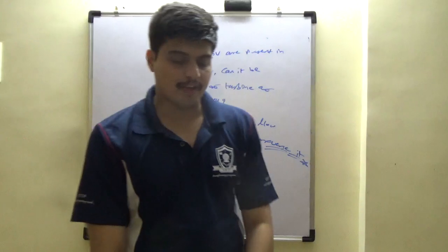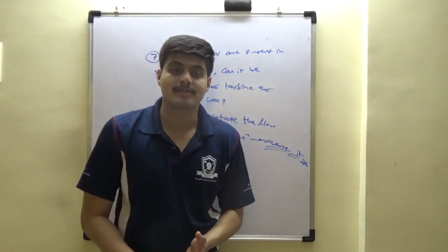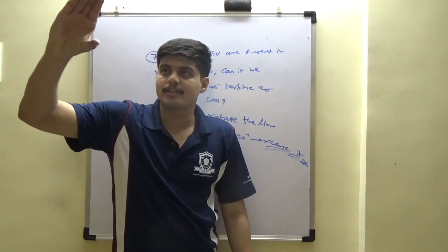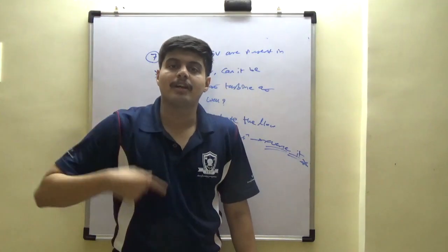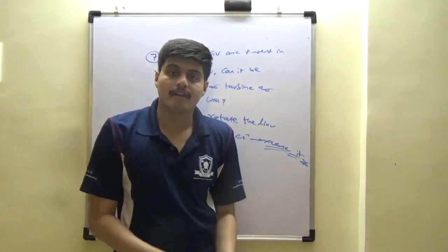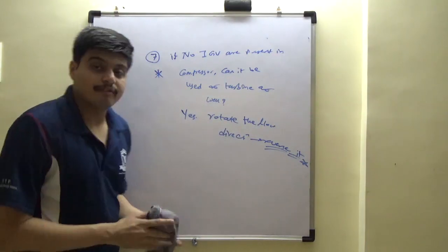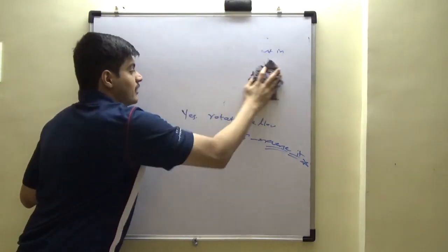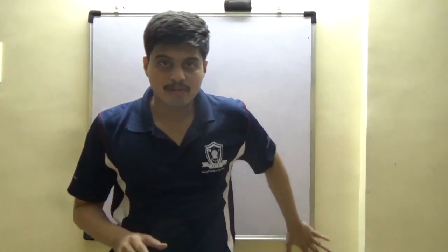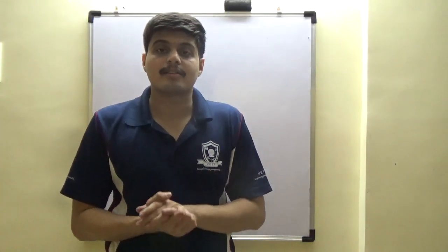Mechanically, there are of course a set of challenges. Something called turbine compressor matching through spools. The hub radius which increases here would not allow your turbines in a small concentrated zone to operate with such a high temperature. So the material science guy there and the mechanical engineer guy there will not let you do it, but propulsion engineering can let you do it. So this is a very good question to understand the nitty-gritties of axial compressor. This closes our tutorial on axial compressors based on the velocity triangle diagrams and a theoretical understanding of compressors.